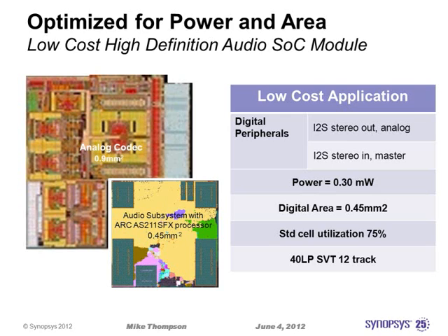So this is actually a layout of the subsystem. This was done with a 211. I put some sizes over there on the side. In the 40 nanometer process, this will run just shy of 800 megahertz, 794 megahertz. So it's certainly very capable. That's a lot more performance than you're going to need in most audio applications. Typically, we see our customers running 300-400 megahertz in the audio environment, and that's if they're doing pretty high-end audio. So again, you see a very small size. This was done in a 40 nanometer LP process.